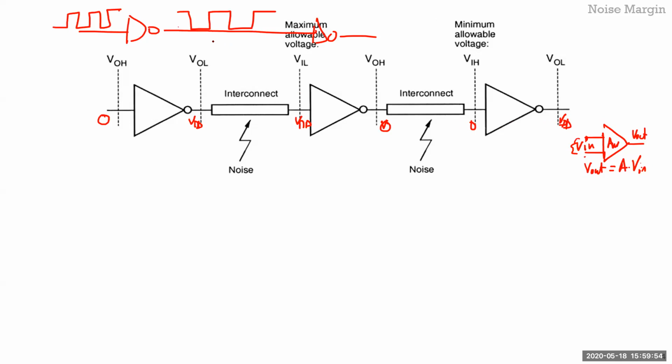Now, in IC design, there is no wire or node in your system which is not coupled to something else with a capacitor. It just so happens that it might be a very small capacitor, but they're all coupled. So for example, there will be a capacitor from this node to this node, and then from this node to ground. As I said, they vary in sizes, but you're always talking about some sort of coupling.